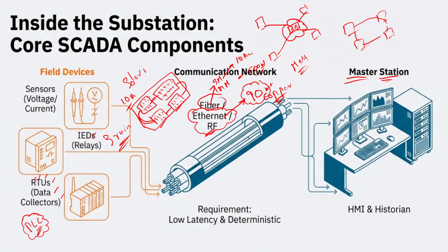So by using this communication network, we can take complete data from the field, and this will be sent to the master station. The master station will have the SCADA systems, right? So it will be processing. One more point is that these fiber or Ethernet cables will be buried under the ground, right? And the second point we have to take care of is the EMI.